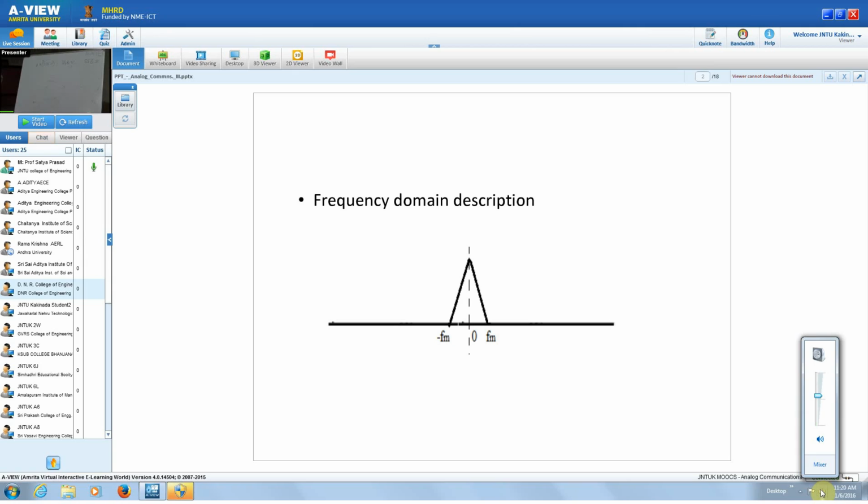That means for AM transmission we require higher power transmitters for the same efficiency. If this is going to be 1 kilowatt that you transmit, this is 330 watts, and this is half of that. So this much power is enough to transmit. Therefore, the transmitter cost of your system in the case of SSB is much less compared to that of your AM transmitter.